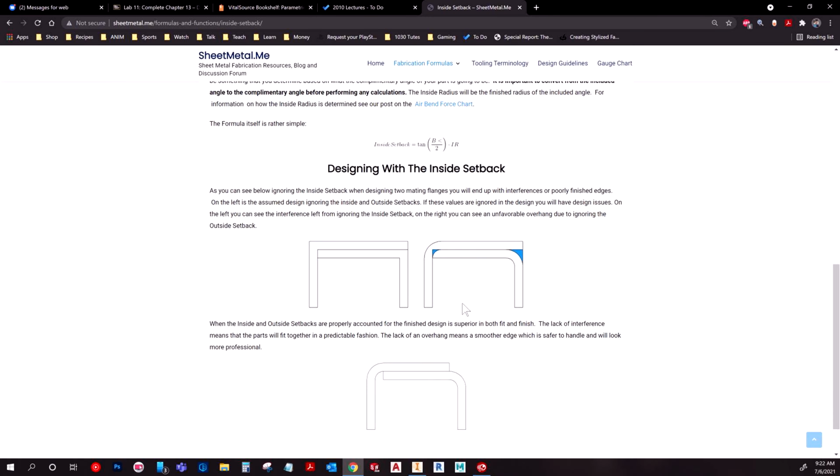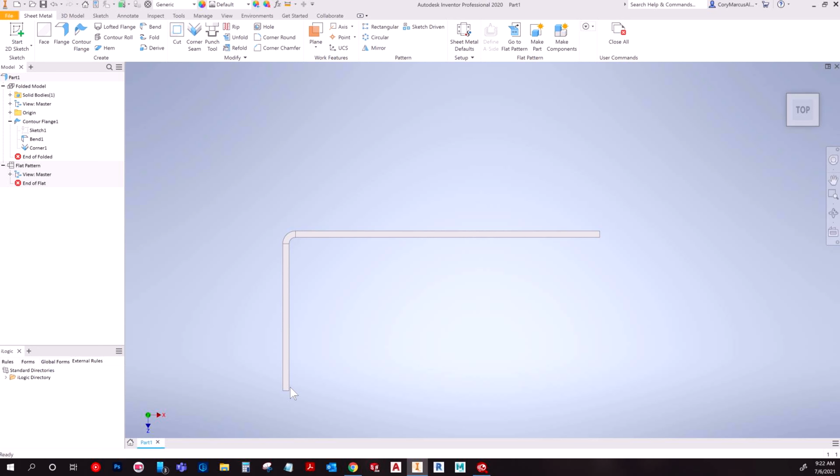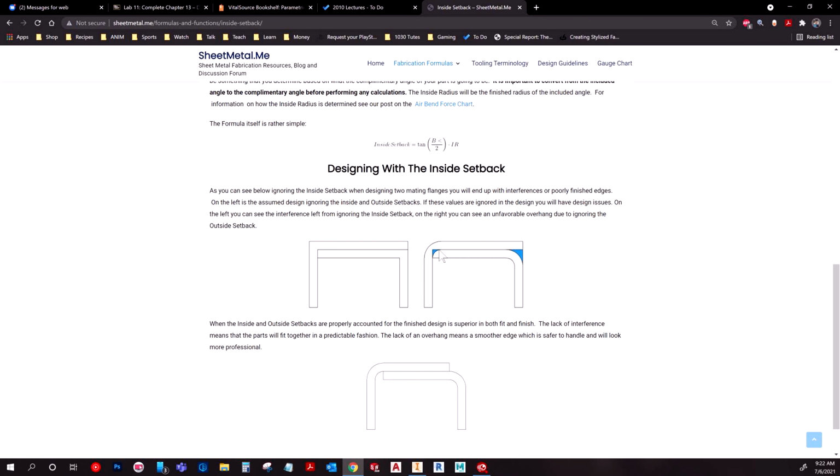And as you get better at it, you'll start to really work on designing things. In this case, it shows that if you made this part imperfectly, you would end up with these sharp edges like we talked about you wouldn't have. But if you wanted to ensure that this part went end to end like this, you would end up having these fillets. But when you're making sheet metal, there is no round edge. You're working with, as I showed a second ago, flat edges. So you wouldn't have this round part. It would just end at the beginning of that bend, so it would cut back to here. Technically, this one could stay there, but it'd be really hard to fill that weld, so they showed the example of trimming this part too.